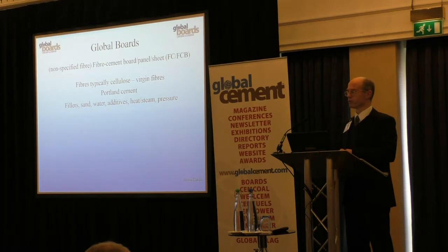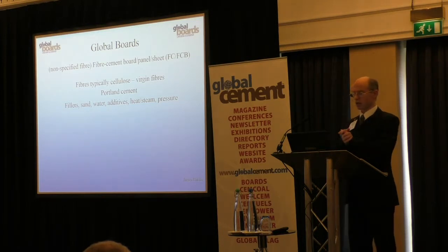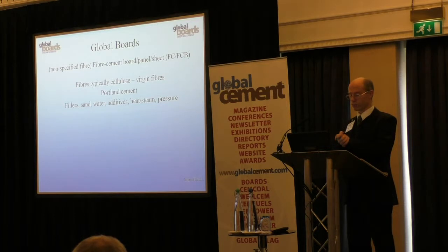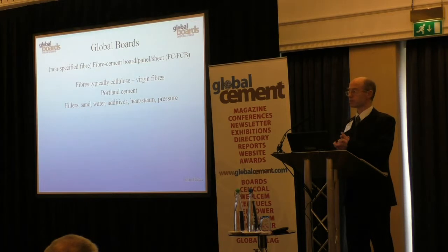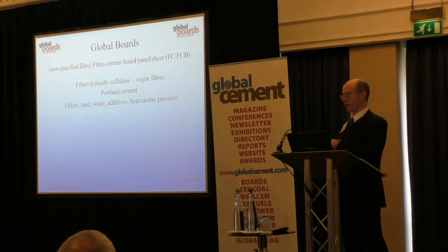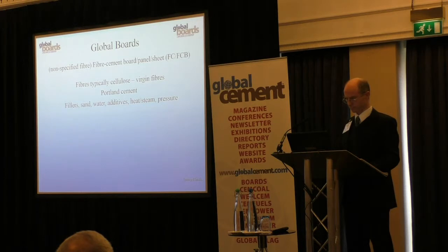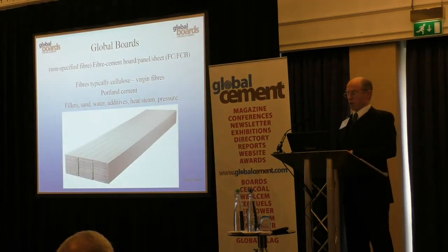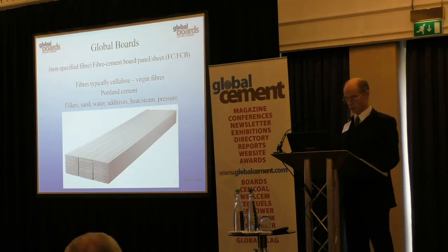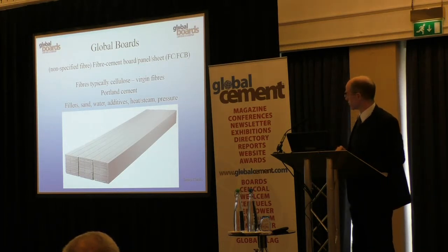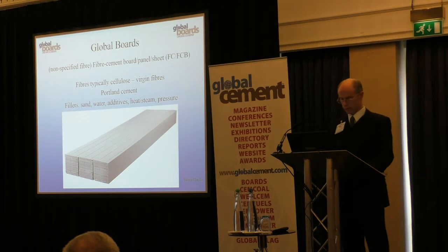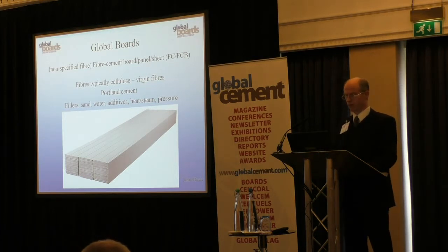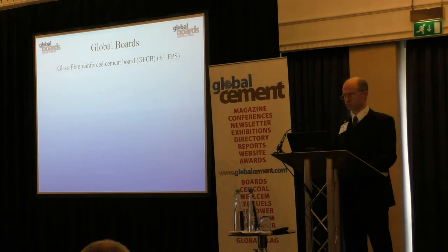And then of course they're using fillers, could be sand, could be a variety of other fillers, limestone's been used, and then of course water, additives, and then a heat and steam and pressure curing phase, typically autoclave, to form these fibre cement boards that hopefully are quite familiar to many of you. And these are boards that are made by James Hardy, one of the leading proponents of fibre cement based boards.